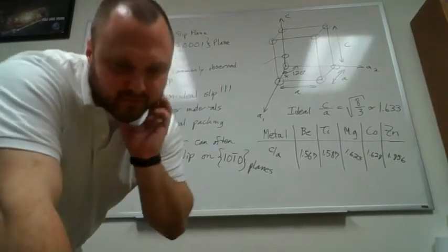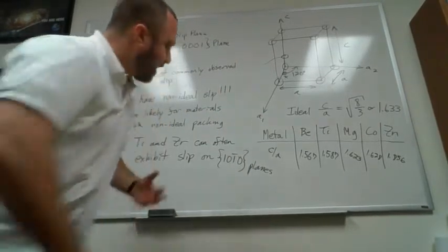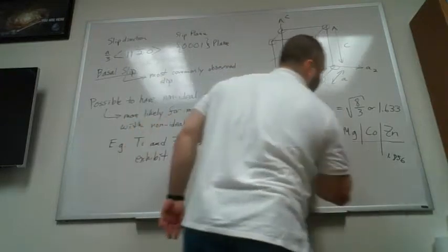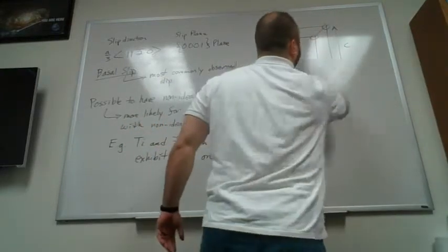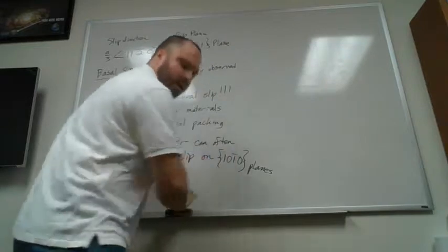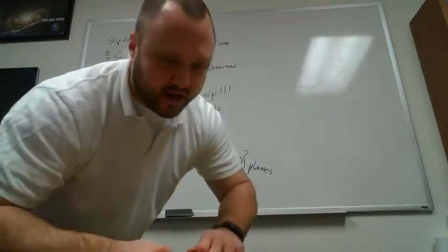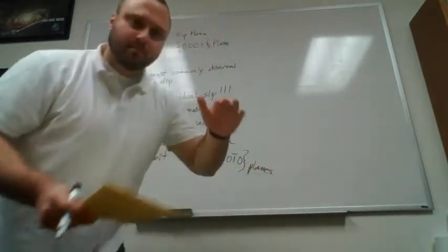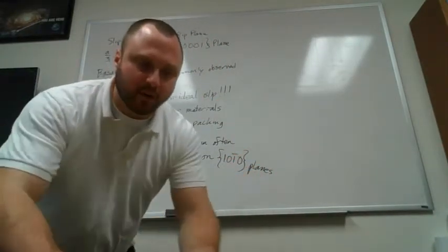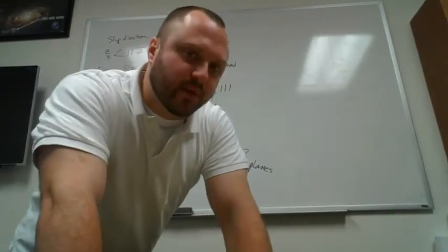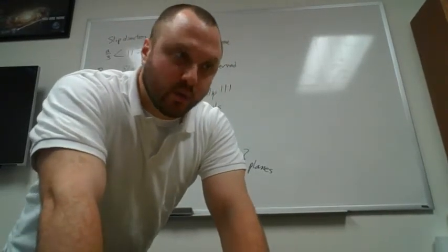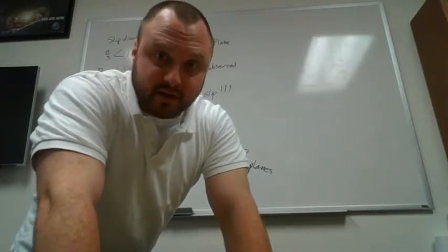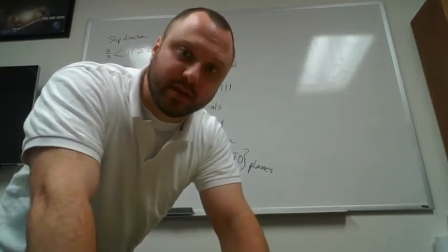But if we think about basal slip, we're having slip on these close-packed planes in the close-packed directions. It's very, very similar to what we saw in FCC. Okay? It's the closest packed direction. But if you remember, what was almost the first thing we did with FCC materials? We said that, well, that's great that these are the perfect dislocation vectors, but is there another path? Can we have partial dislocations? And sure enough, we can also have partials in the HCP crystal structure.